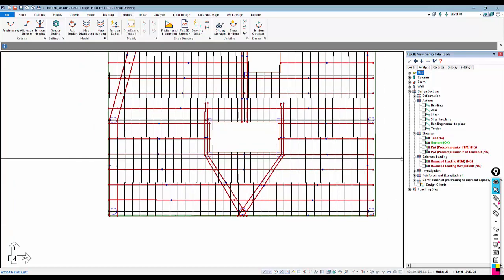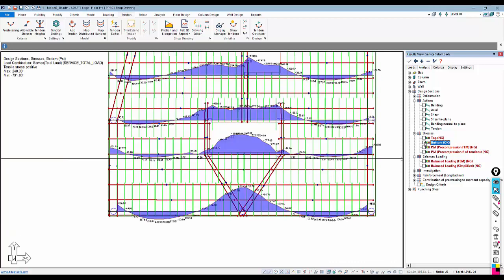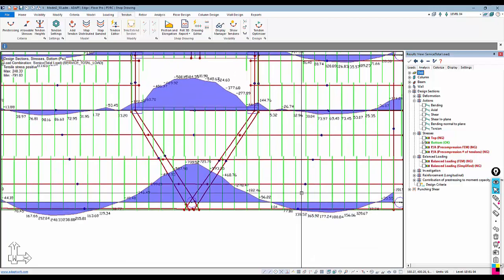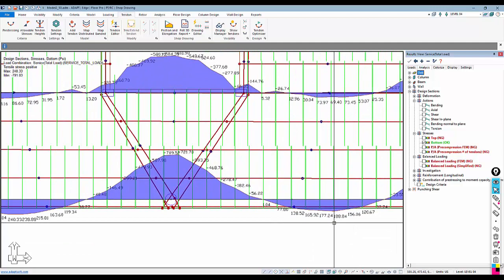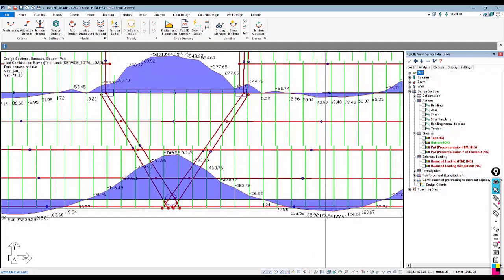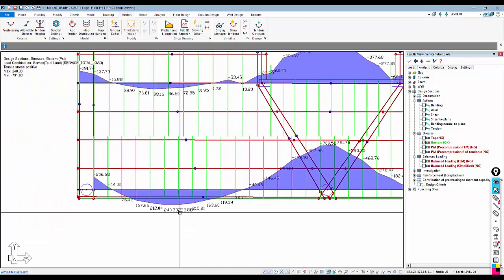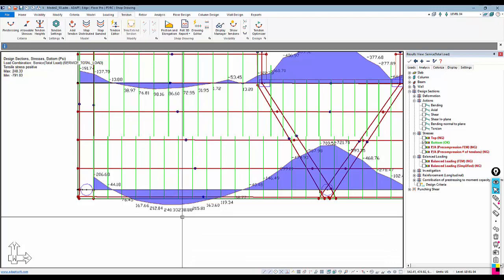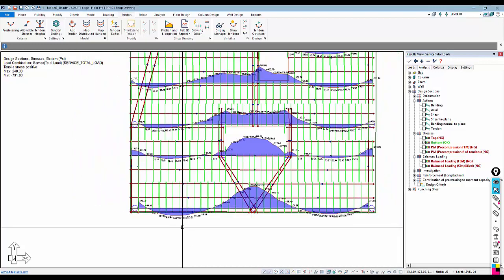Well, what the user may need to go back and check is, what's our stress? If I raise this tendon, this stress is going to grow. So we have, again, flexibility. The maximum is 424. That's the design constraint we've put on this slab, 6 square root of F prime C. We have room to actually lift those tendons to reduce the balancing.